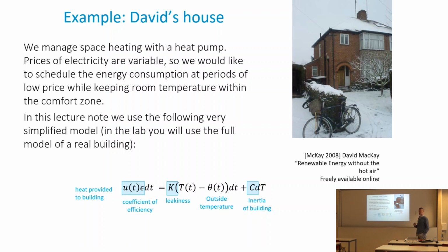It's a good disturbance in that case. The heating comes for free, so if we know that it will be receiving a lot of heat tomorrow, perhaps we don't need to heat as much during the night when electricity is cheap. So those are the kind of things we will need to do. In this very simple example, I assume, like on this figure, that there is no sunshine in a standard UK winter day. So we can leave it, but of course in reality we would need to have it.